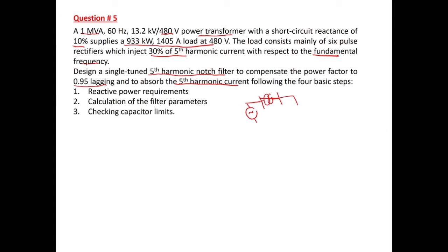So this load takes this amount of power, 699 kilowatt, at a current of 1405 ampere, and the voltage level over here is 480.